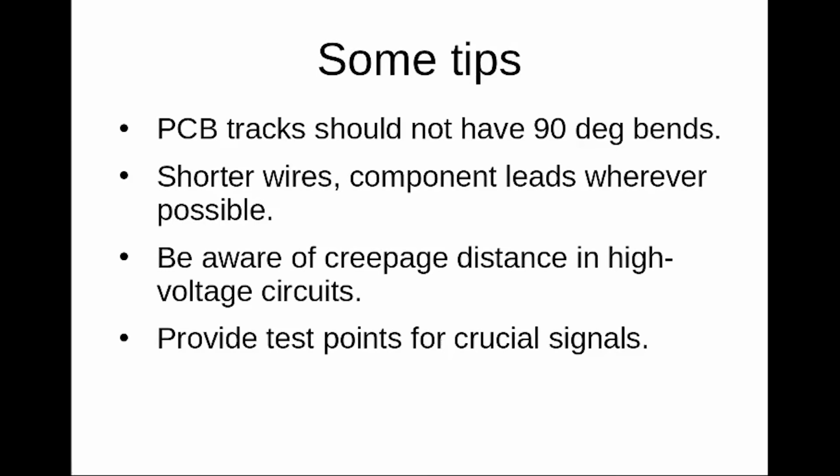Now, while designing PCBs, care must be taken to avoid 90-degree bends in the tracks. Also, we will have to choose track widths as per the current capacity needed.